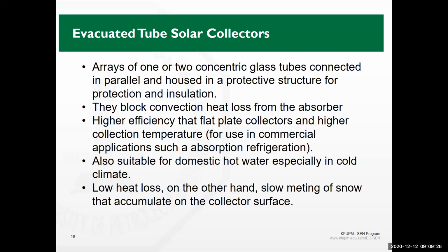A flat plate will get heated, it will transfer energy outside, so the ice melts, but not for this kind of collectors. Then you have to be really careful when you are using them. We are not worried about ice formation in Saudi Arabia, but in places where ice accumulates, like Canada, it can accumulate to something closer to 2 meters high. So evacuated tube collectors might not be the right solution for this kind of environment.